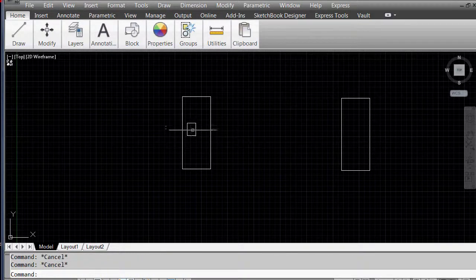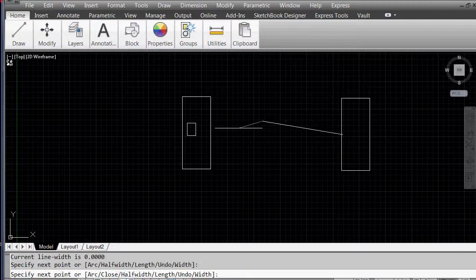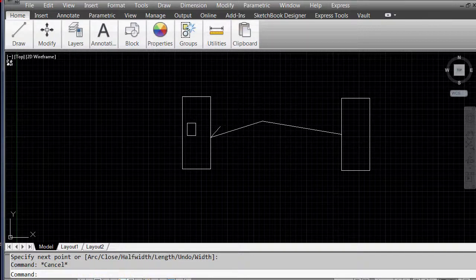You see, the block resides internally in your drawing, so it's what we call live, as opposed to an X reference, which allows you to borrow the picture only. So I open this drawing up, but I can see this picture underneath. I cannot edit it unless I do something very special, but it's there for me to reference. It's there for me to use. That way I don't have to draw all those elements again.